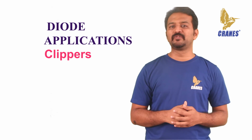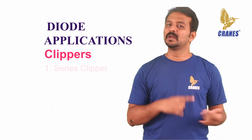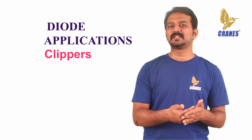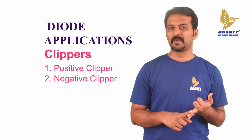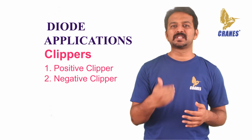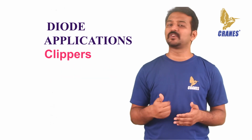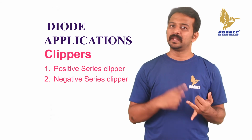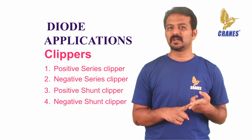Based on the diode configuration in the circuit, these clippers are divided into 2 types, the series clippers and the shunt clippers, and again these are classified into different types like positive clipper and negative clipper. So depending on series and shunt, positive and negative, we get 4 different types of clippers. The first one is the positive series clipper, then the negative series clipper, positive shunt clipper, and negative shunt clipper.